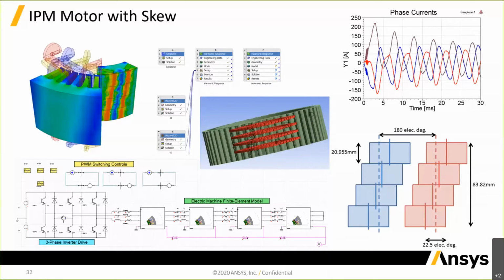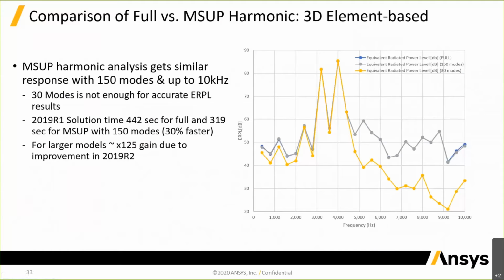But what I did here is I connected up an equivalent circuit model, ran it with some PWM switching at 4 kilohertz across 6 different speeds from 500 RPM to 3000 RPM, and ran it out to steady state, and then used the last electrical cycle at steady state to calculate the forces. And so I'll get back into what that means for us, what that looks like.